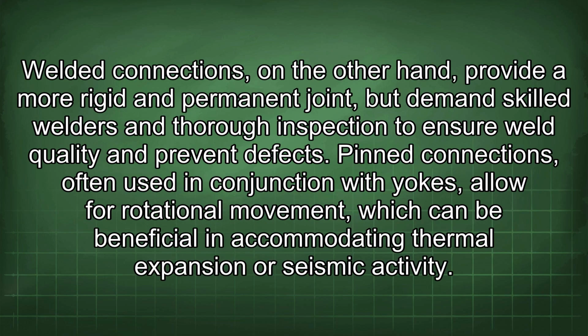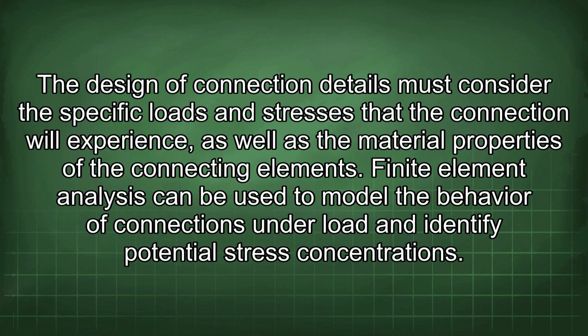Welded connections, on the other hand, provide a more rigid and permanent joint, but demand skilled welders and thorough inspection to ensure weld quality and prevent defects. Pin connections, often used in conjunction with yokes, allow for rotational movement, which can be beneficial in accommodating thermal expansion or seismic activity. The design of connection details must consider the specific loads and stresses that the connection will experience, as well as the material properties of the connecting elements.